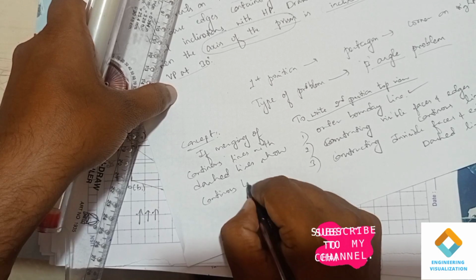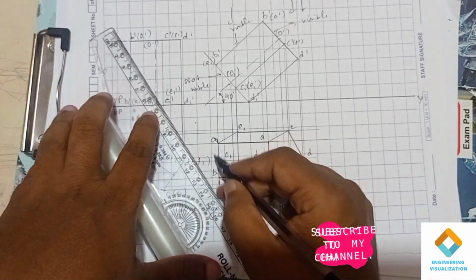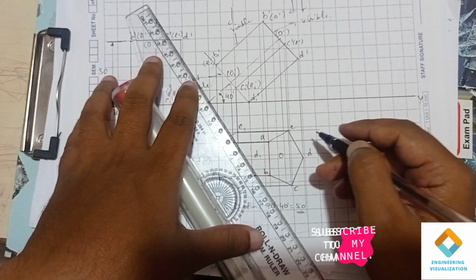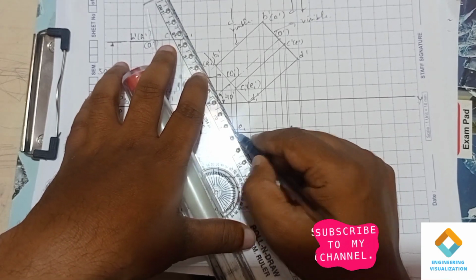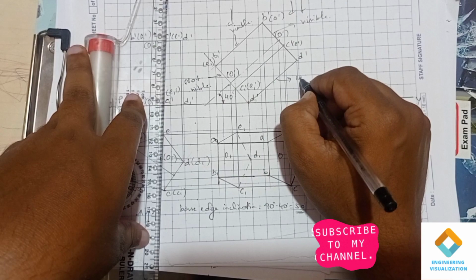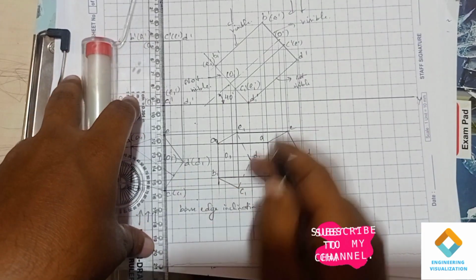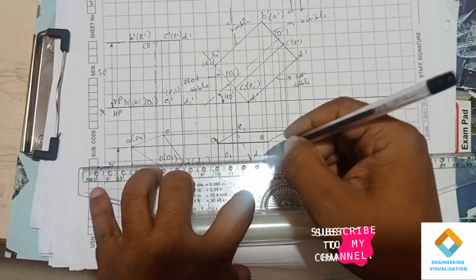That means we will be showing only a part of the pentagon with the dashed line here, because already we have constructed a part of the pentagon with the continuous line. The remaining part we will be constructing using the dashed line here. So try to join with the dashed line here. Okay, now this edge is also not visible from the top view, that is D dash and D1 dash. As we try to write in the top view, it will be from D1 to D. Okay, that will be the dashed line here.